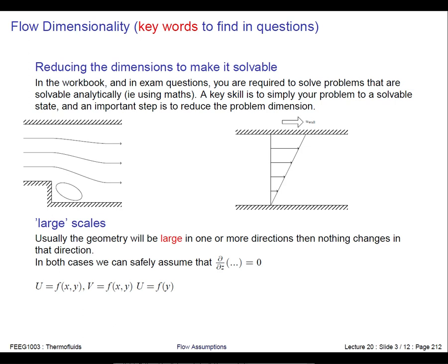So what I want you to imagine, this channel is extruded out of the page, and let's say that's the Z direction, and that means pretty much that there's no changes in the Z direction because there's nothing happening in the Z direction. Okay, so that means you can simplify your velocity field and make your equations a bit more simple.